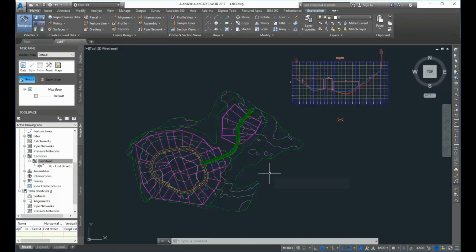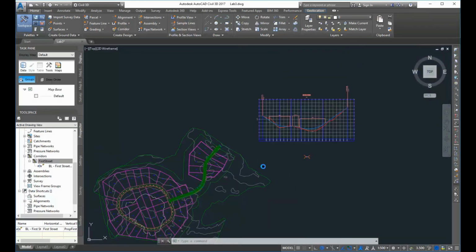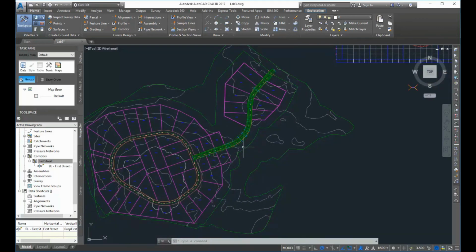Part of the lab, we want to move into starting the steps to determine the changes or the estimated earthwork volumes. So looking back at the profile, we saw from the blue line that there were many places where there was a significant difference between the proposed, or the blue, and the existing ground, the red, which indicate that there's going to be cut and fill volumes or earthwork volumes that are necessary to build the road as designed. So we'll want to be able to determine the estimated cubic yards of cut and fill for our project, which is called calculating the earthwork.